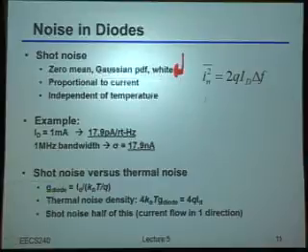So to list this more precisely, the noise density is 2qI_D. And of course, depending upon what your real circuit bandwidth is, that would change the net integration you would get across frequency. By the way, as I also mentioned here, it's independent of temperature.